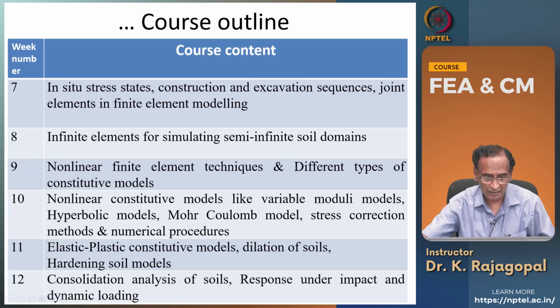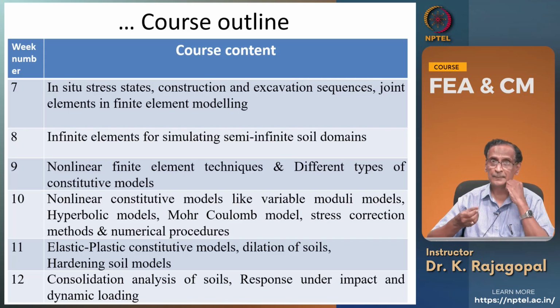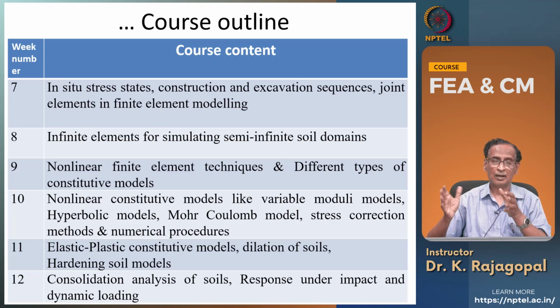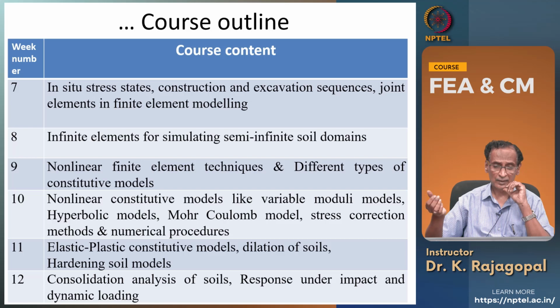And then elastoplastic constitutive models, and how to incorporate the dilation of the soil, because dilation is the volume increase under shear strain. If you have a linear elastic or a non-linear elastic material, the shear and normal strains and the shear and normal stresses are decoupled, they are not related to each other. If you apply a pure shear strain, you will develop only pure shear stress.